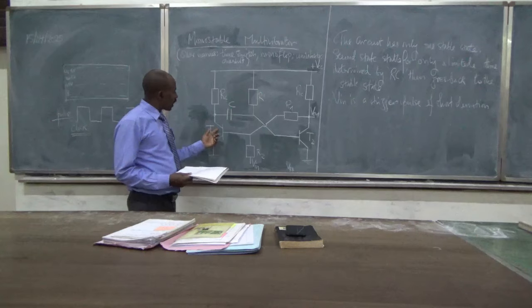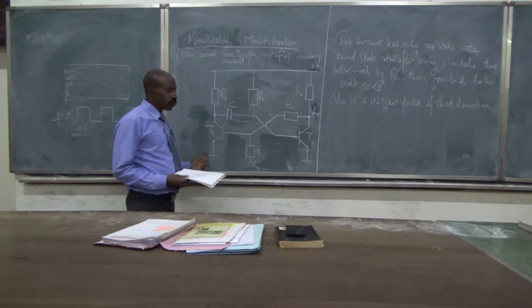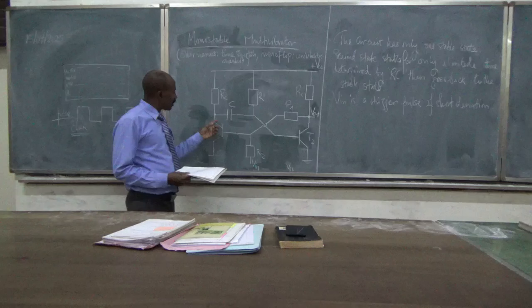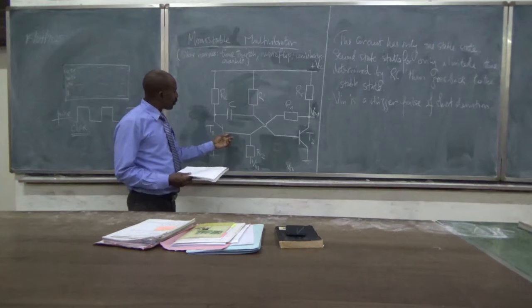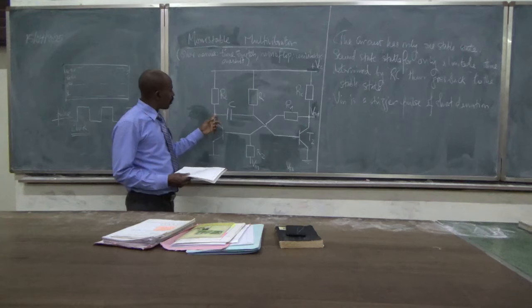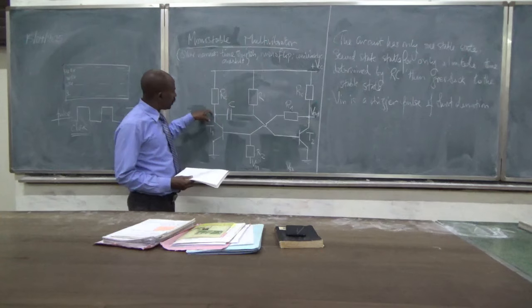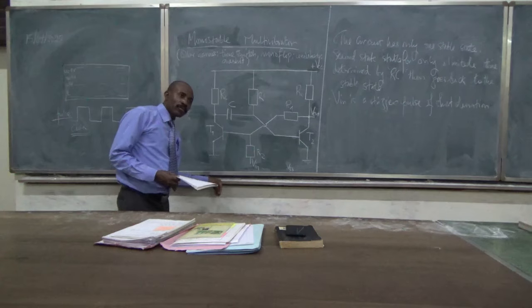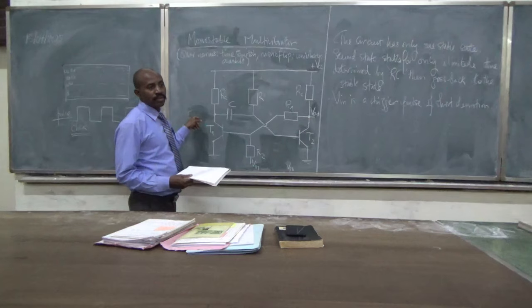When the transistor is conducting, it means that now you have the flow here and everything is going this way. That's why we call a transistor a switch. If it is biased, then you conduct everything, so you won't get anything here. If it is not biased, then you are blocking everything here, that means that you're getting value here. So if there is a lead here, if conduction is taking place, it goes through the transistor more than it will through your light emitting diode.